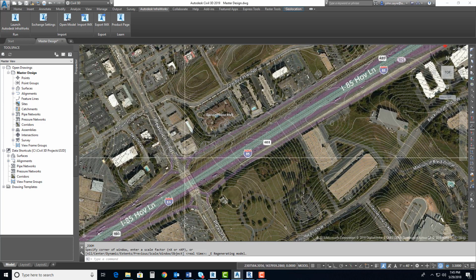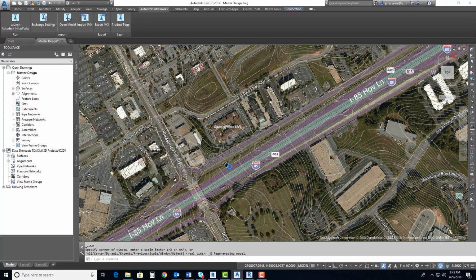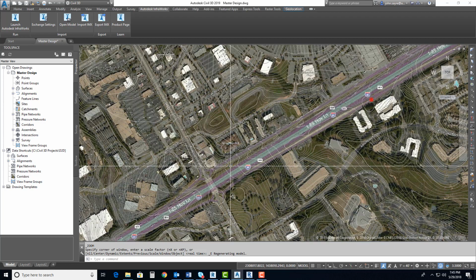All right, so I could bring the point cloud in and verify this, and it would not be a problem. Another way to do it would be to bring in the linear features. After I get my linear features in here, I can actually create a boundary around this surface and then know that I have just the area that I need. So the first thing I want to do is bring in my linear features that I extracted.